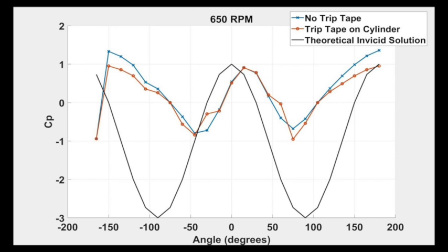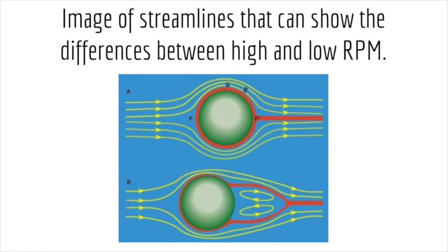Therefore, on the front half of the cylinder, you have a formation of boundary layer, as well as separation of that boundary layer as you move across the cylinder. Theoretically, the cylinder should not have drag due to symmetry in the y direction, but in our experience, we see drag due to the imperfections in our system. We have systematic errors in the wind tunnel, like electrical conversions of the reading into data and holes in the wind tunnel messing up the flow.